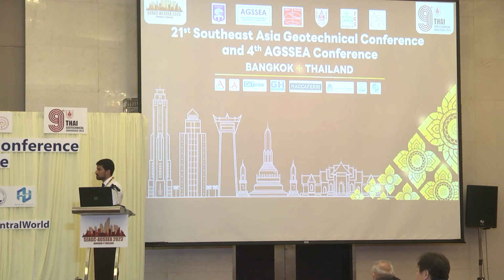From the literature, have you seen any other people using the PM4Sand model to mimic the behavior of gravelly soil like yours? Like Haber et al., the paper which I have used, they have used the PM4Sand model. Right, but that's mainly for sand. Yes, but for this type of soil, would that be applicable to the gravels from your standpoint? Yes, I think that's a very good point, because generally, even if they are gravel, the percentage of sand is the dominating one, and that's why we are using the PM4Sand model. At the moment, from preliminary research, I can say that it's also applicable, but maybe in future there's going to be a new model. Now we have PM4Silt for more silty soils, so maybe for gravel or bigger particles, there's going to be a new numerical model which can be used in future. All right, thank you.